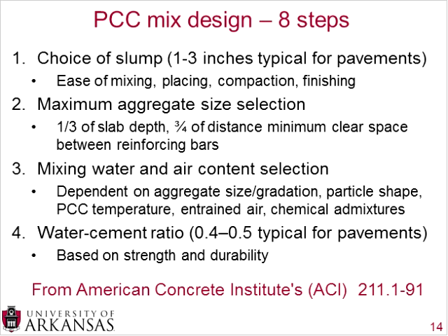So transitioning into mix design practices. As we go through these 8 steps for PCC mix design, I will have included some general values for pavement structures. PCC is obviously used in much more than just pavements. It's used in foundations, in building design, all these different applications. So if you go to the American Concrete Institute's ACI 211.1-91, which goes over the mix design, they have to plan not only for pavements, but also for all of these other applications.